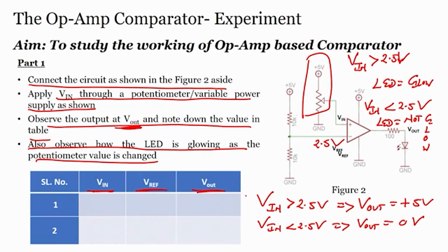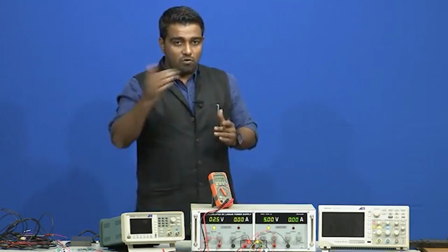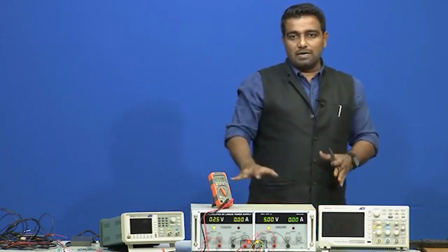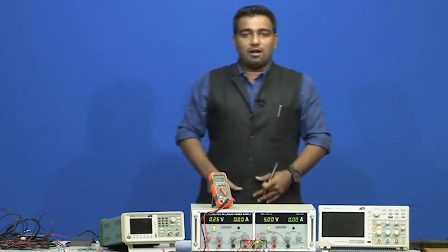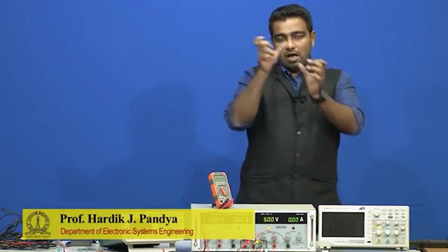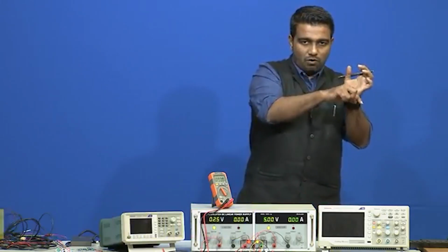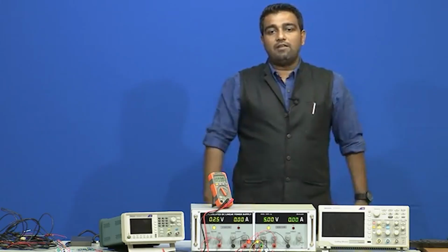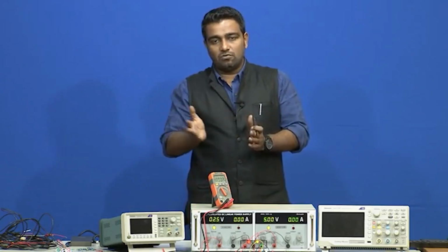Now, all of us can perform this experiment of a comparator. You can go tomorrow and start doing a comparator and you can glow the LED. So, understand this thing, until and unless you ground the circuit it will not finish, right, you cannot keep on hanging it. So, same thing when we are using an LED with a current limiting resistor, you have to ground the LED, right. So, one is resistor, output, resistor, LED, ground, alright, and cathode is ground, not anode is ground, cathode is ground. So, an LED works in forward bias, you should know it.